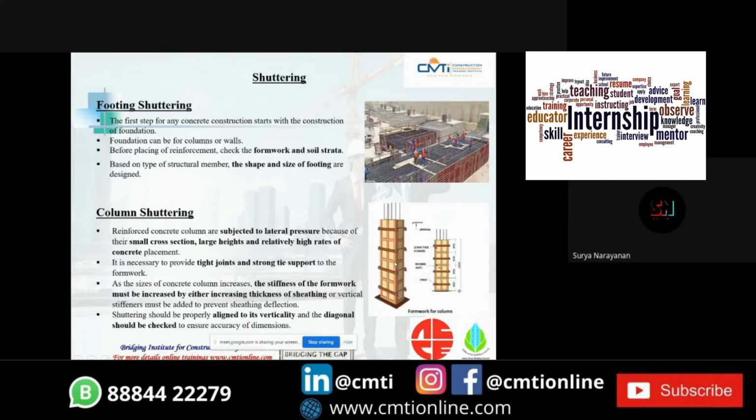So next is shuttering. This is footing shuttering, because it is the first step of any concrete construction. It starts with the construction of the foundation. Foundations can be of columns or walls, and before placing the reinforcement, we should also check the soil strata. The size and shape of footings are designed based on the type of structural member being used.